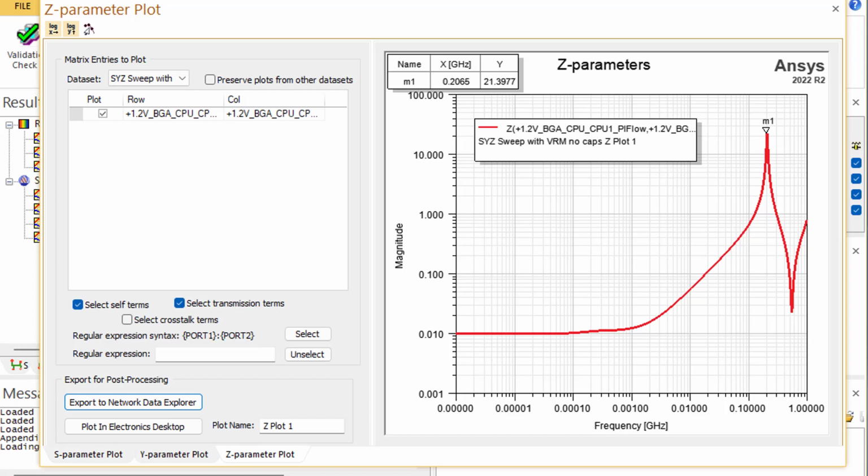But where, and what value, and how many? The resonant mode solver will only answer the first question: where to put the decoupling caps. By the way, from this plot, we determine the range of frequency where we are looking for our resonance. So for this case, for example, we're looking at a resonance at 200 meg. It means I want to solve within this range to be able to see this mode.